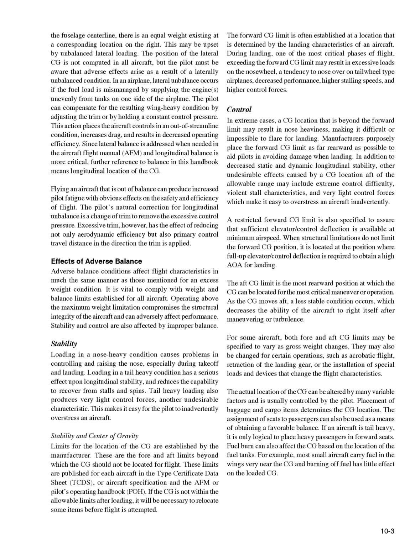Effects of adverse balance conditions affect flight characteristics in much the same manner as those mentioned for an excess weight condition. It is vital to comply with weight and balance limits established for all aircraft. Operating above the maximum weight limitation compromises the structural integrity of the aircraft and can adversely affect performance. Stability and control are also affected by improper balance.